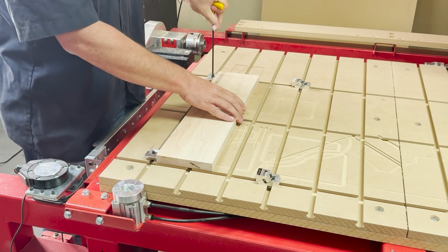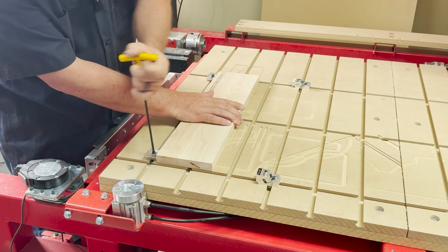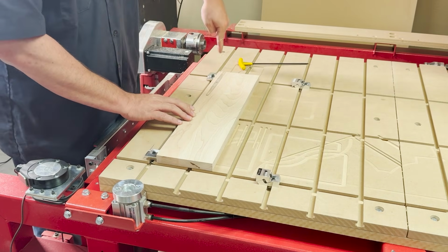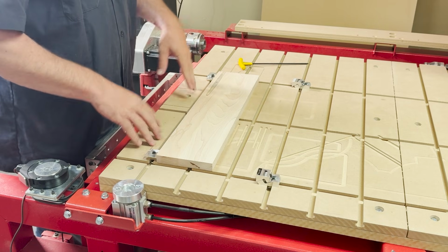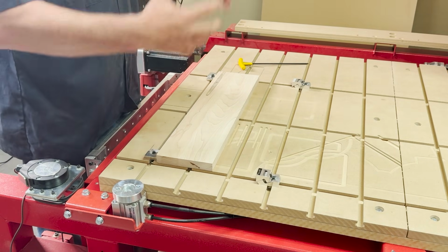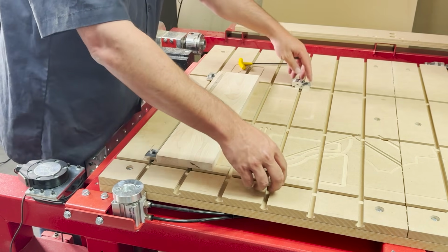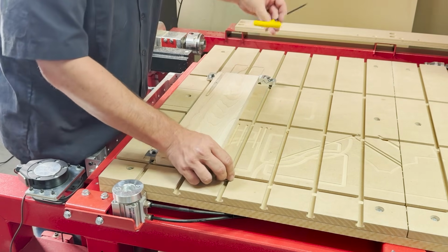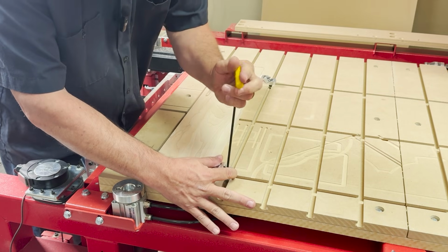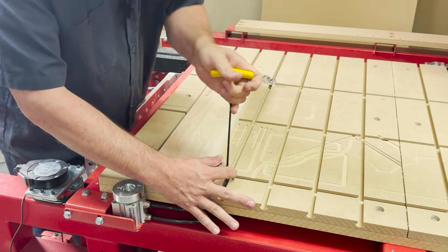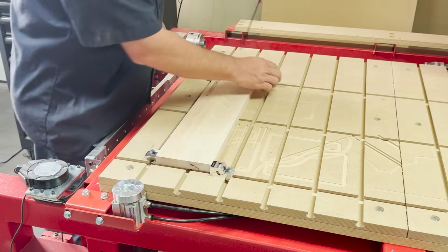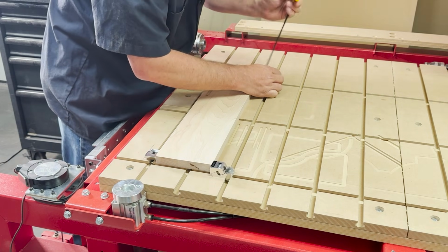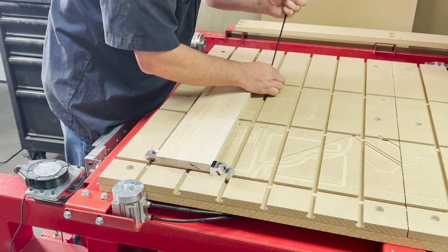So as we snug these up, what you'll see is that I get a nice parallel to my Y-axis cutting. So my Y-axis is going to be right here, and because both my T-track table and my clamps were set up with the machine, I know it's perfectly parallel. Now I'll take my clamps, and these are just going to grab on the ends, and that's where I want them. We'll first set this screw into place. This is the screw that's going to hold it onto the table. When that one's done on both of these, then we'll set our clamp into place. So let's go ahead and get both of these ready to go.